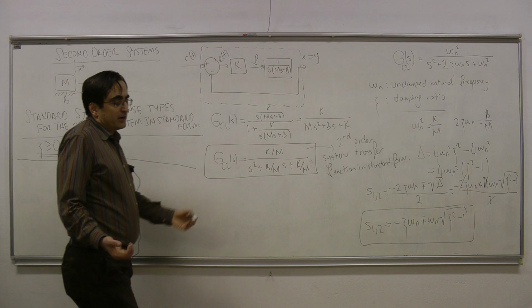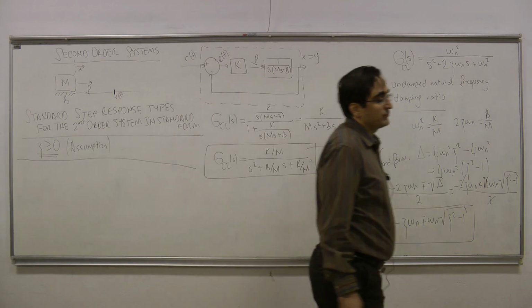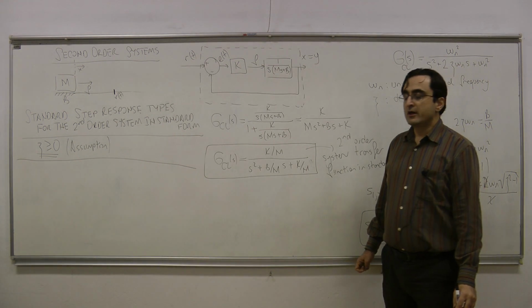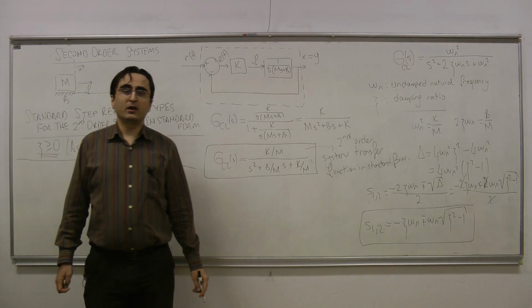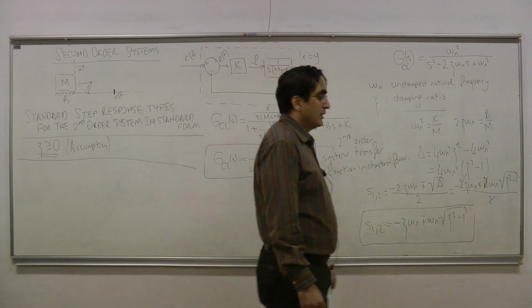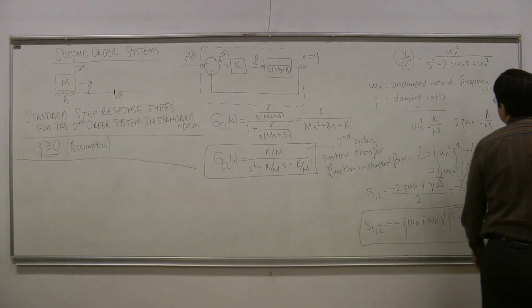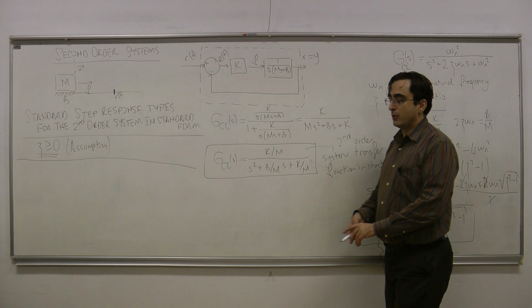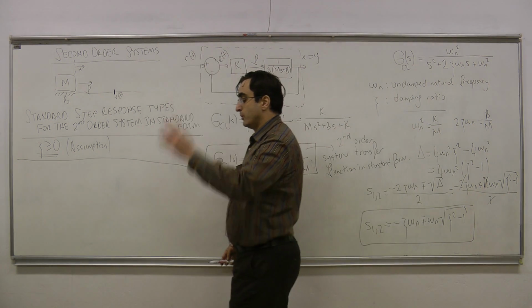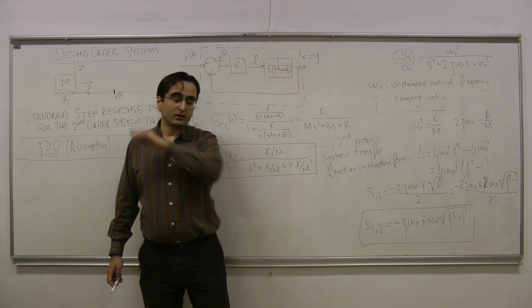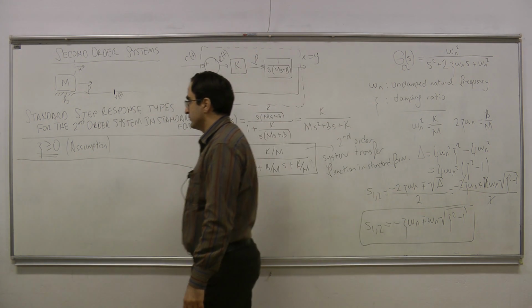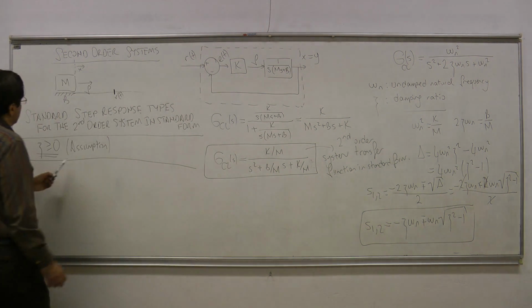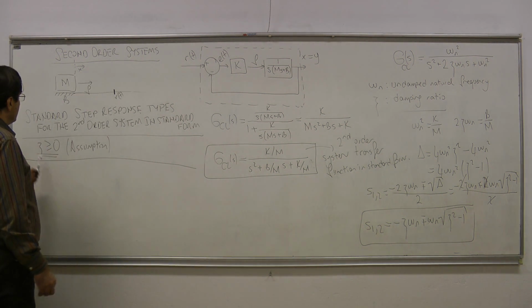In general, then you might ask, what happens when this parameter is actually negative? In that case, we are going to see that the closed loop system would actually be unstable always. So what does that mean? That means that when I look at the step response, the response would be going towards infinity, either by oscillating or just pure divergence, non-oscillating divergence. So that is why we are assuming that this parameter is larger than or equal to 0.